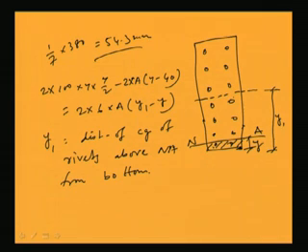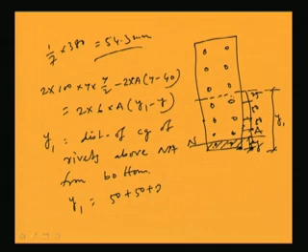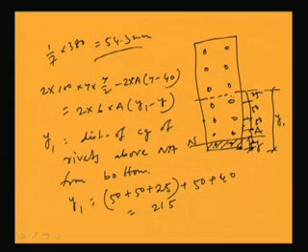So, we have to calculate first up to this distance, then this. So, this will become how much? That means 50 plus 50 plus 50 by 2, this is 50, 50, this is 25, then this is again 50, from here to here 50 and then 40. So, y1 will become 50 plus 50 plus 25 plus 50 plus 40, which is becoming 215 mm, right.